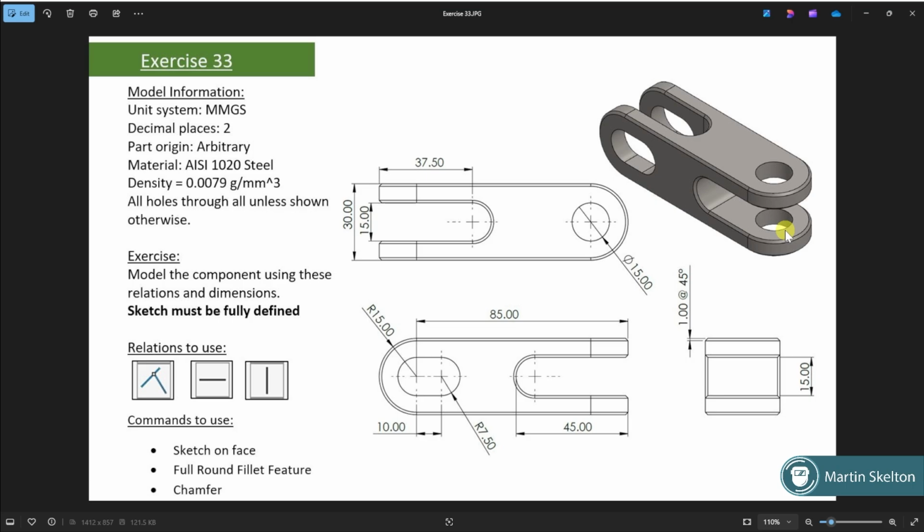Okay, so we have identified that we're going to start with either our top or our front plane. Well, I'm going to just pick my front plane. Doesn't particularly make a difference. The information I have on my front plane, if I look at my drawing here, is that this is the top view looking down. We can see that because of the position of the hole cuts, etc. So that's looking down. We then have a front view looking this direction, and we can see that with our holes the way they're laid out as well. And then this final one is looking in that direction.